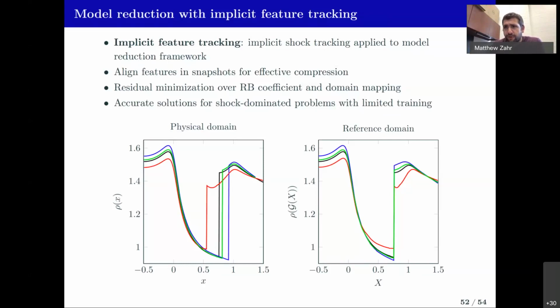We were able to do 3D supersonic flow over that cylinder in MATLAB. We were able to do the flow through that scramjet in MATLAB, and we just use direct solvers and things. So it's not like they're cheap to do, but because of how dramatically you can reduce the number of degrees of freedom needed when you track shocks, you can do these more complicated problems on not traditionally high performance computing platforms. And we are extending it to domain decomposition and fully implicit solvers to be able to push to harder and more complex problems. But I guess the summary is, yes, they are more expensive, but we use coarser meshes, so it doesn't really affect us.